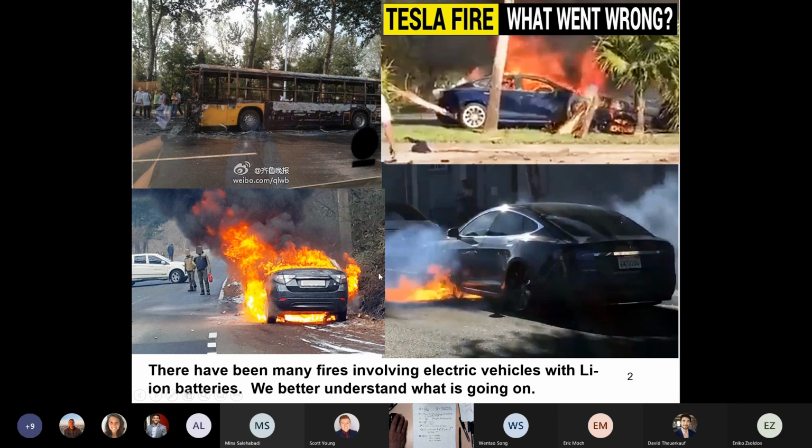If you think about EVs and the safety of lithium-ion cells now, it's incredibly different. It's probably one incident in several billion cells, and maybe even lower. The main contributors to that are precision manufacturing, the separators with ceramic coatings on them, better electrolytes, and so on. But we really need to understand where the issues are coming from.